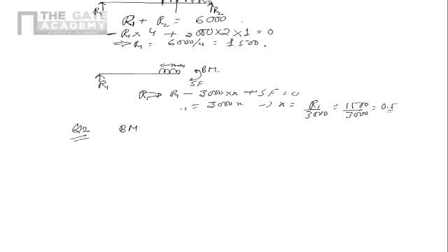So the bending moment, using the same diagram, we can see will be found out. Bending moment is anti-clockwise plus; the moment because of R1 is negative, minus 1500 into 2.5, plus that span is 0.5 and the value of Q is 3000, so that becomes 1500 into 0.5, is equal to 0.